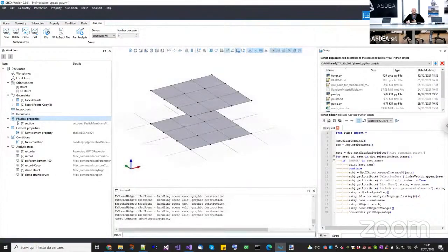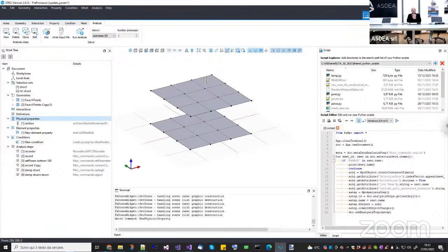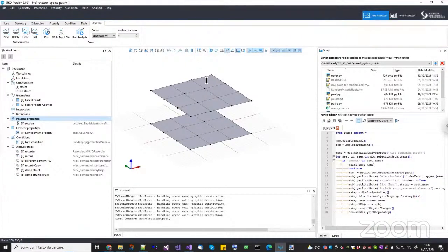Then you told me about the base rotational stiffness. I imagine that you're talking about the connection between the bottom of the pile and the soil. Is it right? Yeah. Okay, so in that case, you need to create a zero length connection. Do you know how to create zero length elements in OpenSees and STKO? Yeah, with an interaction, you create a zero length.